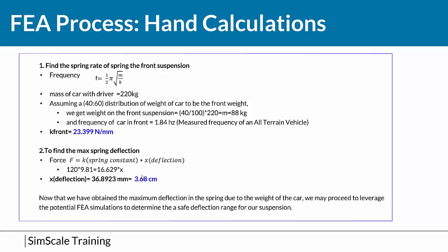And you also must remember that the spring has the smallest circumferential area, or cross-section area, and hence the stresses go up. So what we are trying to do with this simulation is limit our stresses due to a displacement to a value which is lower than the yield point, such that the spring in the suspension does not plastify.